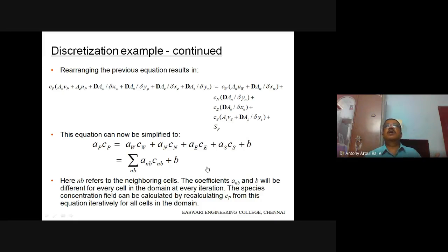So you will be giving the boundary condition on the east face, west face, north face, south face, front face, back face. All the information is going to get transported. Because of this connectivity only, all the information is getting transferred. What is that information? The information available at the boundary is getting transported inside. In a one-dimensional problem, the information is available at the end point, and it is getting transported inside.